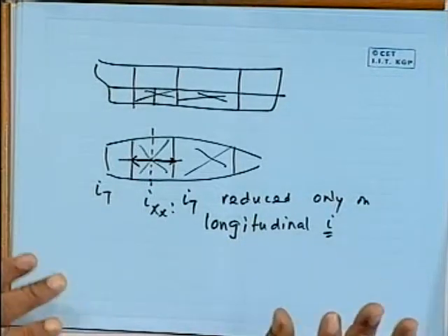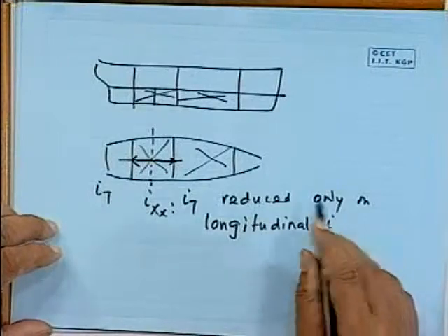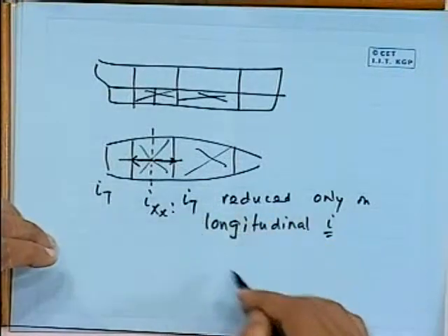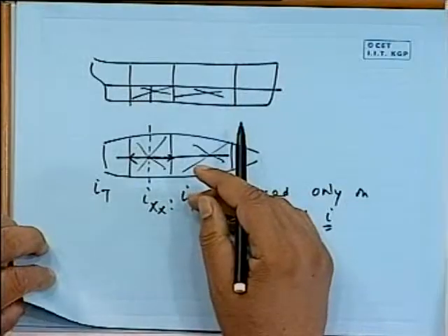I of the vessel, I of the tank. This is actually extremely important. Free surface reduction is very significantly affected by longitudinal subdivision. That is why almost all ships will have at least one longitudinal subdivision, a centerline bulkhead. All tanks would have at least that; you don't want to have anything less than that. So this is the question of free surface, which sometimes becomes very critical. You see how it can be critical.